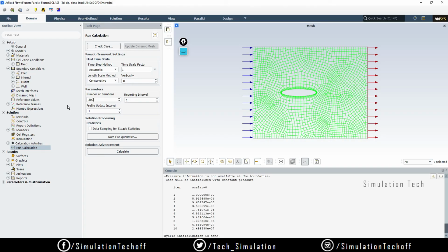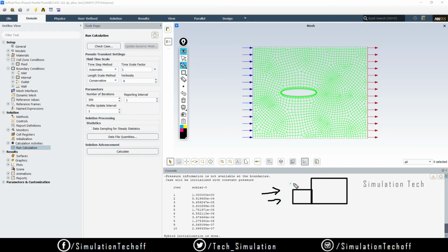So what is a reliable or appropriate boundary condition? In some cases, you may give boundary conditions which are beyond the limit. Suppose we have a car structure like this and you want to find an air drag analysis. You'll assign the velocity. This car moves at 80 km per hour. It's a reliable one. So 80 km or 40 km, there will be some range, right?